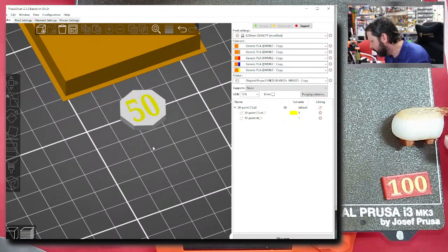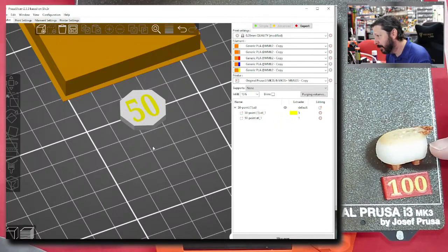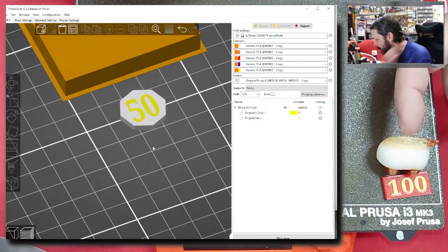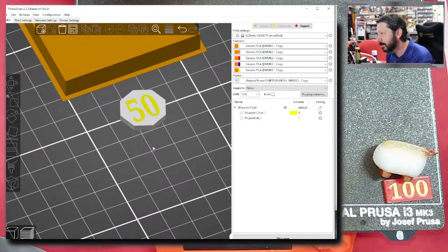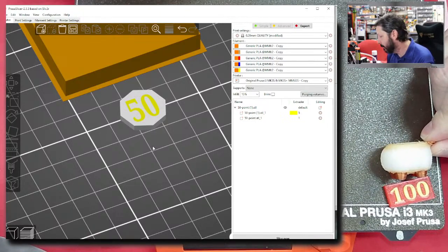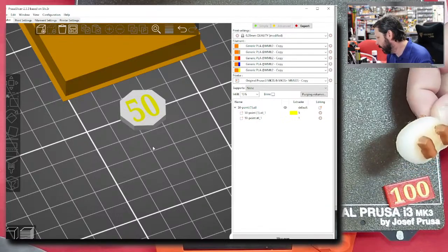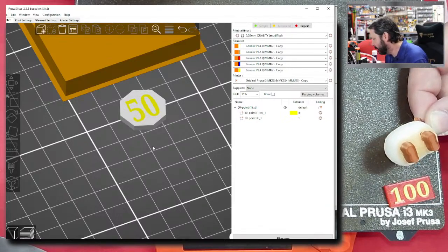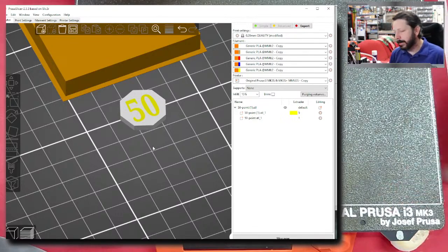But you can see how it's perfectly white when it doesn't have to mix, like right in here. But then this is the same color at the top, but it's having to purge this little bit of gold. And you can definitely see there's a tint to the yellow, so it didn't purge well enough. Same thing on the bottom where his feet were. But he came loose. He didn't have a lot of surface area holding him down, and that was before I was spraying the bed and had cleaned it and everything.